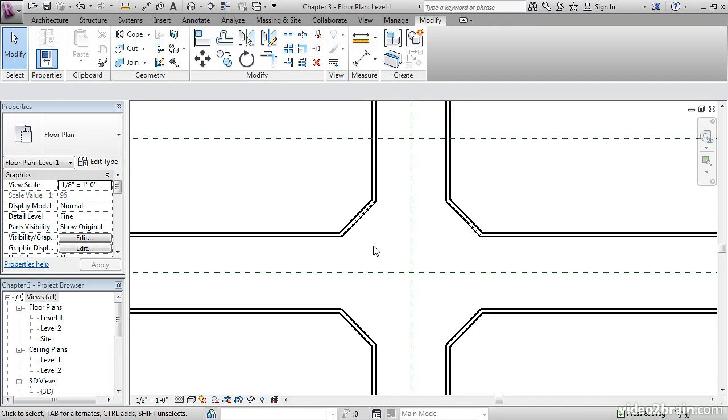In Revit, you're going to find yourself in this exact situation many times over. Now that you know how to set reference planes, then modify your walls, delete the reference planes, cut some corners, trim some stuff out, you're going down the right path, or in this case, corridor.